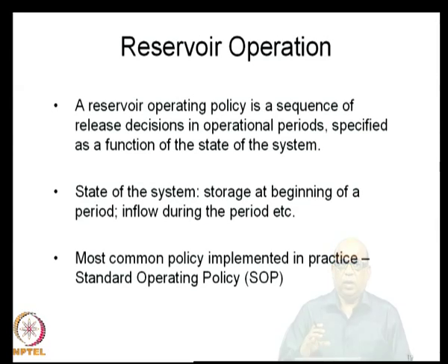It is like meeting the demands to the best extent possible in each and every time period. That is a standard operating policy. That means, we do not look beyond. We simply look at the current time period, look at the storage available, and account for the inflow that is likely to come during this time period. So, that will give you S plus Q, that is the storage plus the inflow, which defines the total amount of water available during that time period.